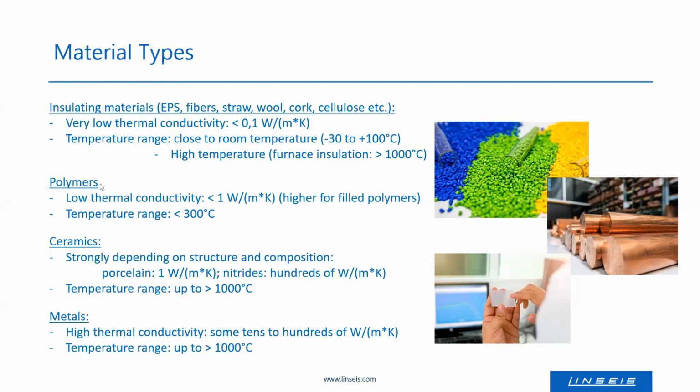Polymers have a slightly higher thermal conductivity, but it's still a quite low thermal conductivity. And the temperature range of interest is usually below 300, often even below 200 degrees centigrade, because at higher temperature the polymer will decompose or melt, and it has no application at high temperature.